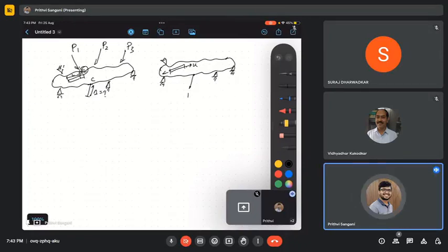This is displacement inside, these are the strain displacements, right? Because of external load, what are the internal displacements? And because of the external unit virtual load, that virtual load will make it 1. So 1 times delta is nothing but summation of U times dl. If you are applying some virtual load P, that will be P times delta, but we want to find out delta, so we substitute the virtual load P as 1, and that will be unit load. So 1 times delta is sigma U times dl, and delta will be equal to summation of U times dl.